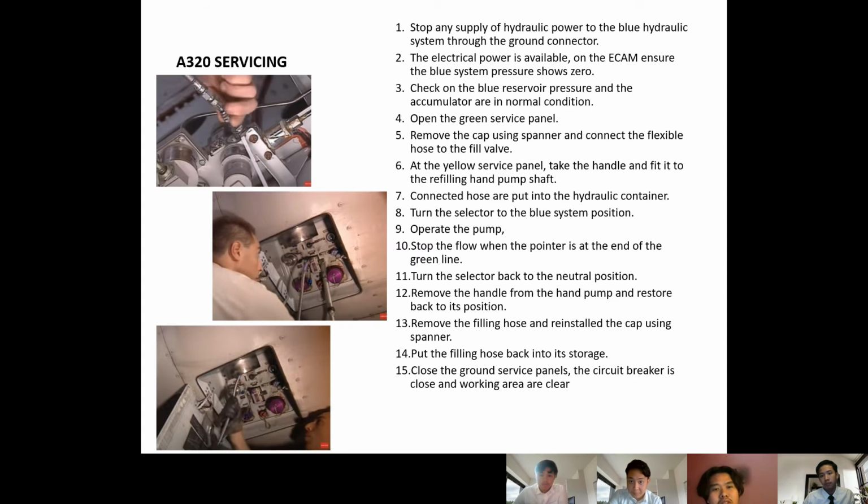We continue to A320 servicing. Firstly, stop any supply of hydraulic power to the blue hydraulic system through the ground connector. Secondly, electrical power is available on the ECAM; ensure the blue system pressure shows 0.